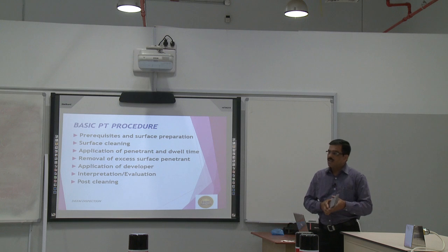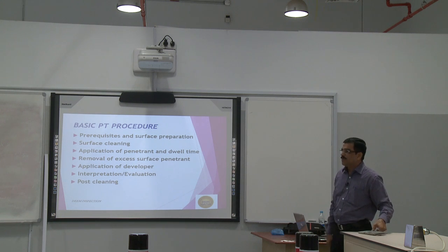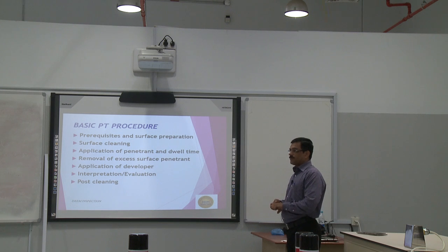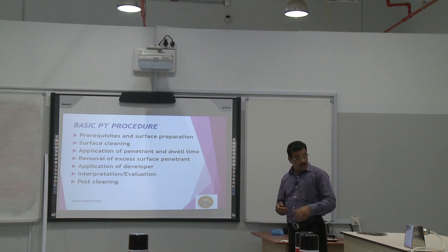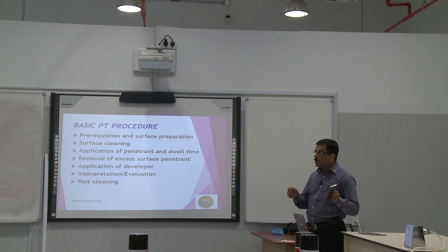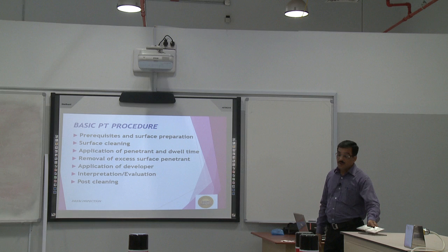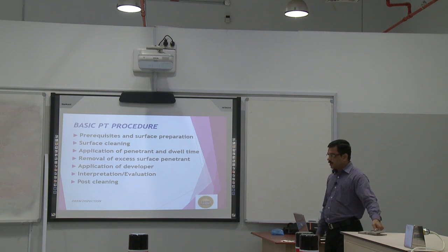But at most sites they are doing grinding, power brushing, everything. Usually, in the as-welded condition, they only do manual power brushing. In usual welding conditions, they are not going to do grinding again, only manual power brushing, wire brushing.